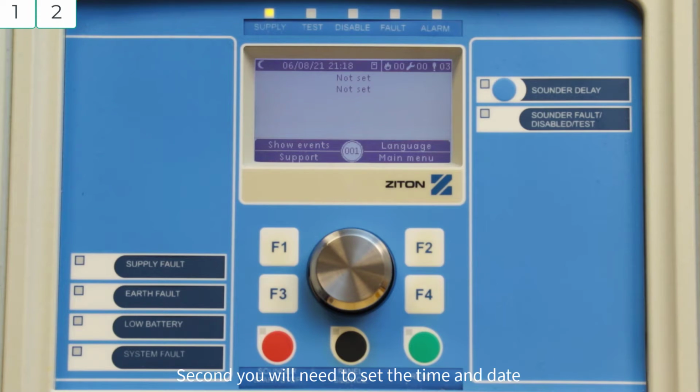Second, you will need to set the time and date and run the auto setup process, so that the panel is fault and condition free. The third task will be to configure the panel using the panel configuration software. So let's talk about task number 1.